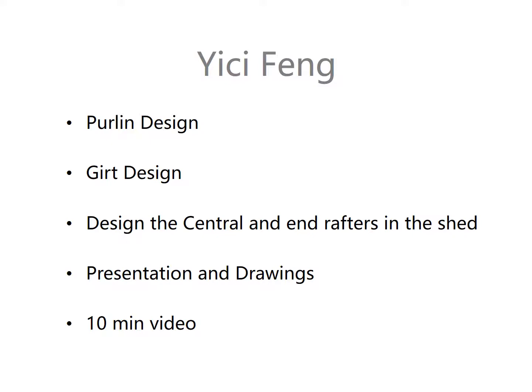In the rafter design, we can find that different spans and the overall shade length can lead to different results. First, in the rafter design, we should guess the rafter self-weight in the design loads, and then we need to put the rafter self-weight into the dead load and live load. And then the combination of actions will need this dead load and wind load.